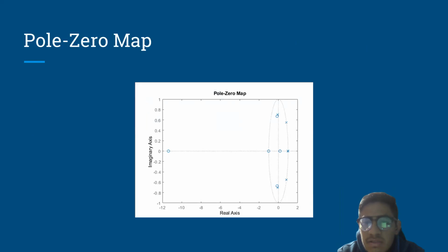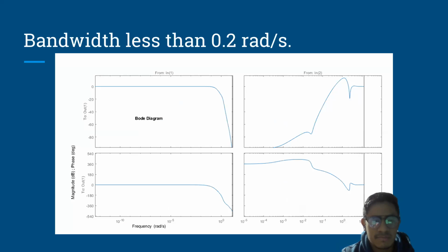As we have seen in this simulation, the pole zero map, the poles and the zeros obtained must stay within the unitary circle. In order to do this, both the real and the imaginary values must be modified. Finally, with the poles we decide, we have to interpret the graphic so we can see if we comply with the requirements.